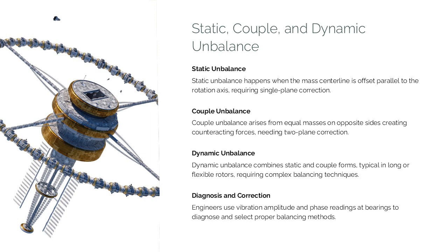Dynamic unbalance combines aspects of both and represents the most complex form, commonly found in long or flexible rotors. Engineers diagnose these using vibration amplitude and phase readings collected at multiple bearing locations. Understanding the differences ensures that the correct balancing method, single-plane or two-plane, is selected and applied effectively.